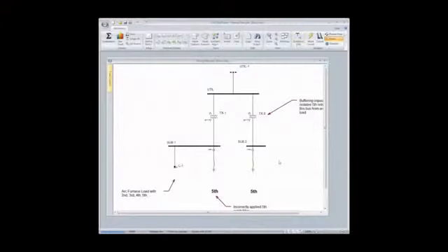So going back into the harmonics focus, running a distortion, great, we're at 3.7, we're fine, but we want to do some power factor correction. If we were to have designed this filter at the fifth harmonic, wow, that's not really a good condition. We basically increased our distortion up to 25%, and that's not a really good application.